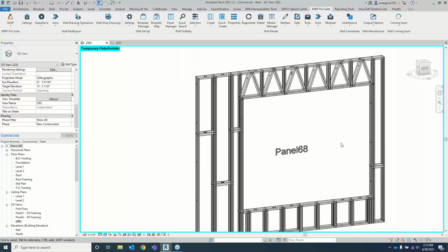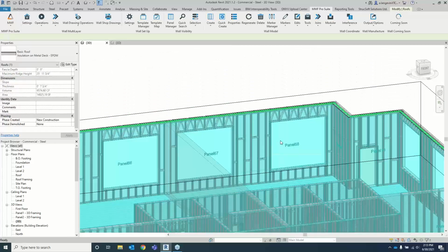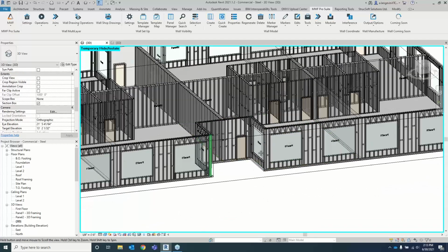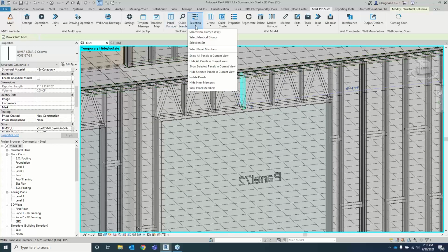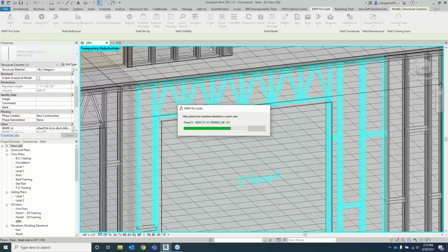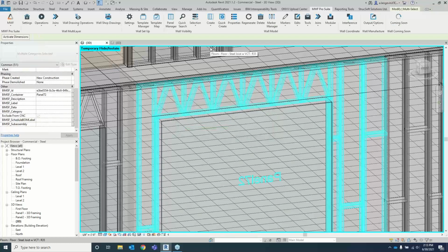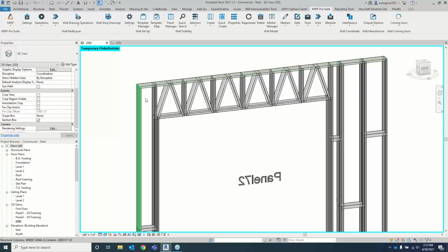All right. So I'm actually going to switch panel right now. Reset this. We're going to pick one more panel. So one that I haven't worked on, I think this one right here. So now the option that I'm going to select is the offset option. So basically this allows you to place your whole series in a specific location. So it's not going to do the entire panel horizontally, for example, or vertically. I can assign the hole to be just at the top or just at the beginning of my panel.